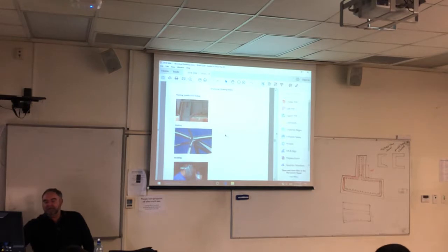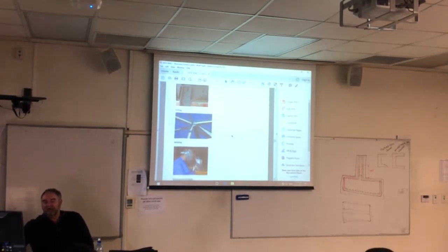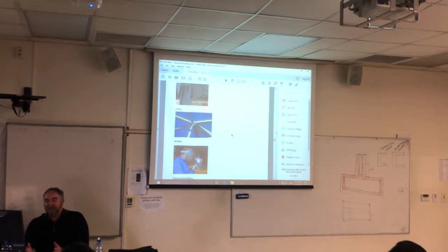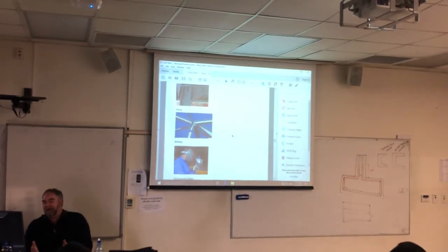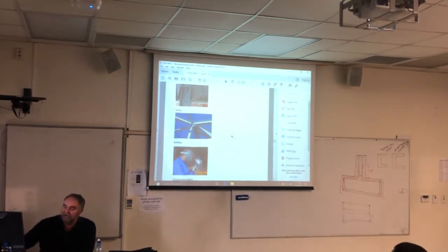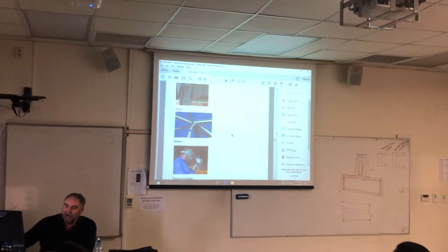Welding is used more for site manufacture, for site welds. It is fairly rare to do welding on site, but they do use welding cutting machines on site. So the connection of choice for most engineers when they're doing any design is bolting.